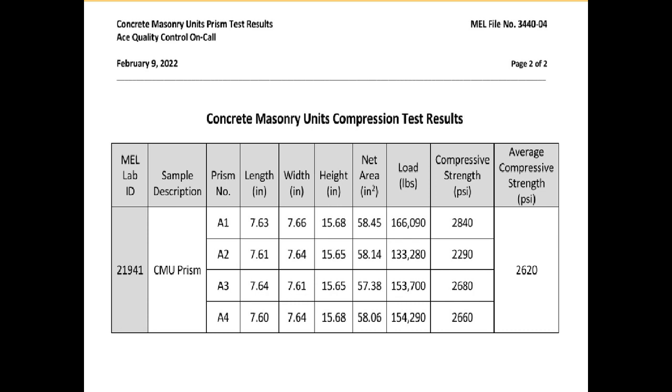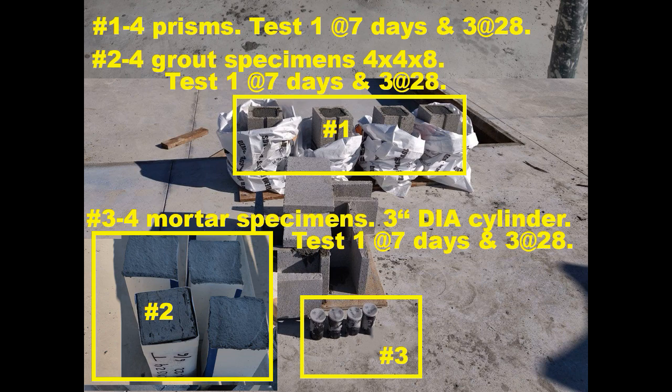If the likelihood of low-strength masonry is confirmed and computations indicate that the load-carrying capacity may have been significantly reduced, tests of cores drilled, or prisms sawed, from the area in question may be required. In such case, take 3 specimens for each prism test more than 500 psi below the specified value.